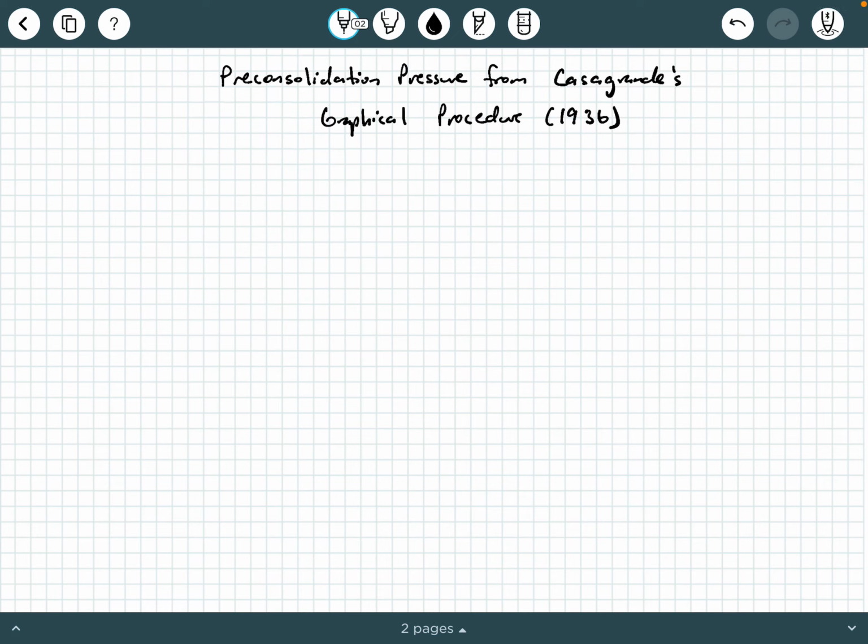In this video, we are going to discuss how to determine the pre-consolidation pressure using Casagrande's graphical procedure, which he developed in 1936. So if you recall, the pre-consolidation pressure is typically called sigma prime sub P, or sometimes we call it sigma prime sub C. But again, this is called the pre-consolidation pressure.